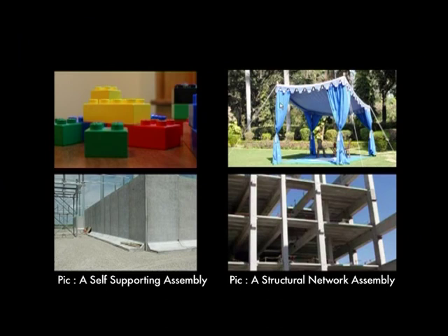If you see the bottom picture, you can see that the framework has been raised in a building and the infills, the openings between the framework, will be filled by lightweight materials like bricks or blocks or any other kind of material, thereby allowing you to construct faster, at the same time giving you the flexibility to have different sizes of windows and doors.